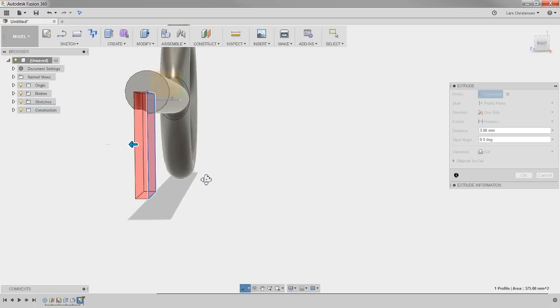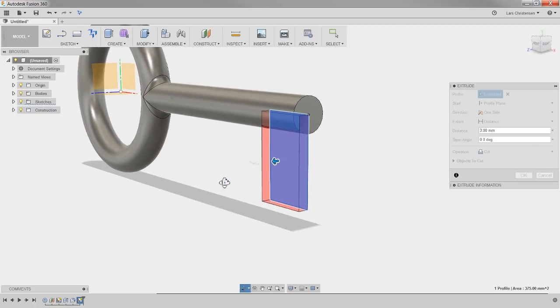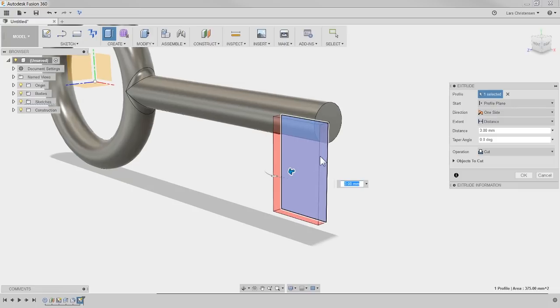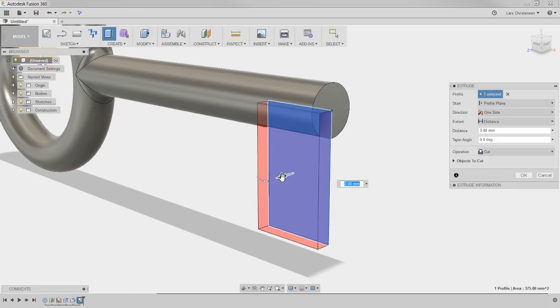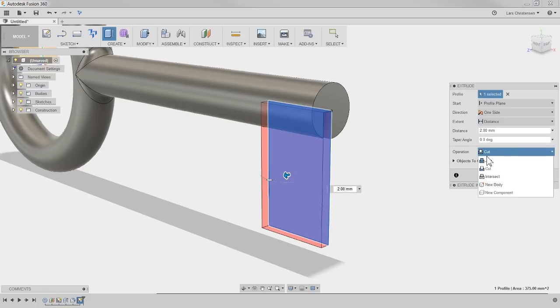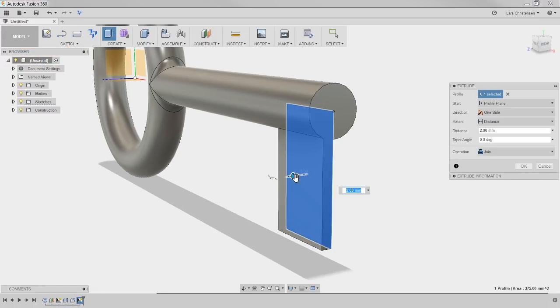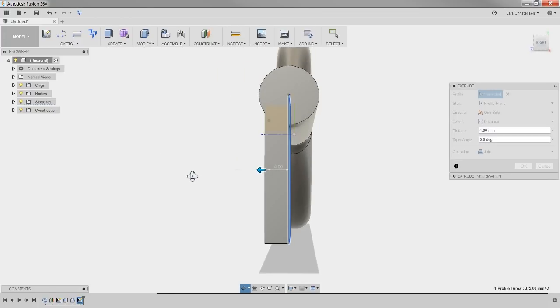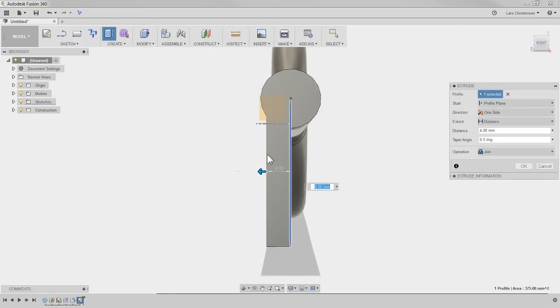well, actually, it goes into a cut because, as I told you before, when we did the rod into the part, as soon as two things are intersecting each other, like we're doing here with the sketches, it wonders if it's a cut. But again, that's just another drop down over here. If you go from cut to join, then you will now see that we get that solid, and it now looks a lot more like a key would.